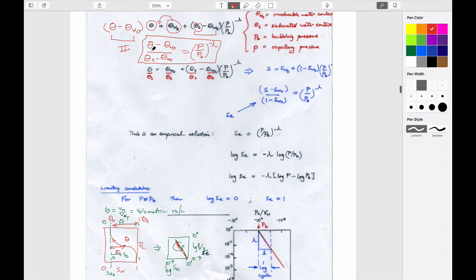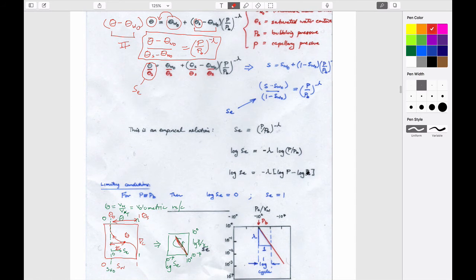If you take this relationship and you divide every single term on the left-hand side through by the volumetric moisture saturation when it's fully water saturated, then each of these terms individually becomes a saturation, or an effective saturation. It doesn't matter. I think I'm talking about things that perhaps don't matter so much to you. Bottom line is, we're able to get a relationship that allows us to map this curve onto this curve.